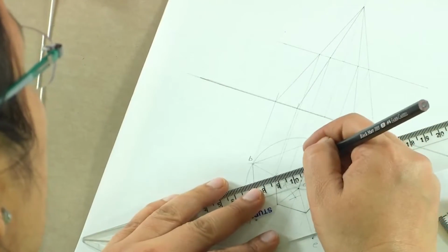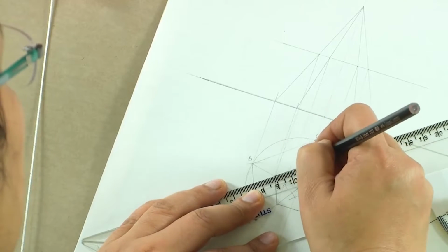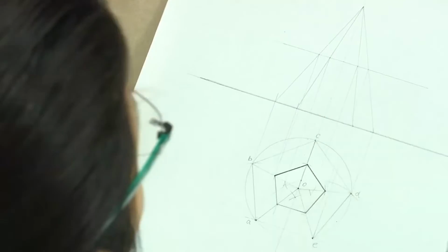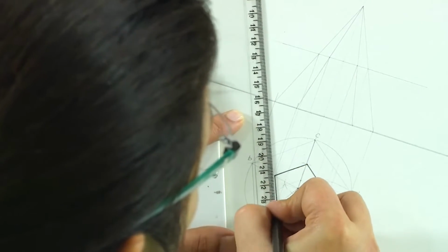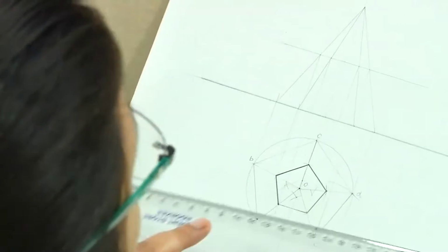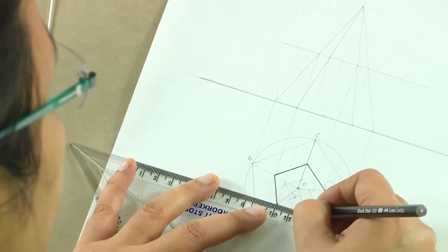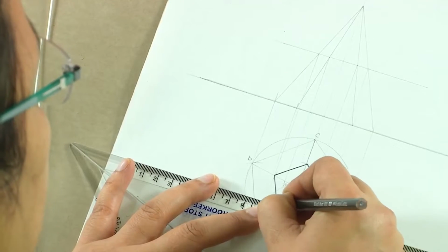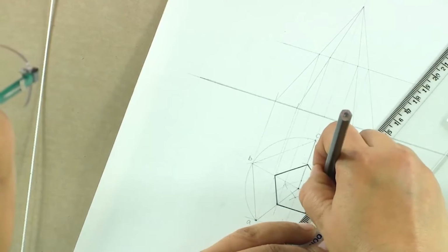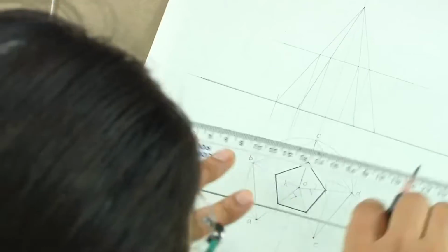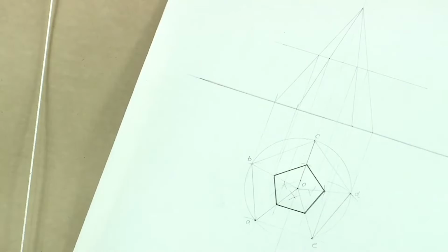we arrive at this point like this, and this is the final shape of the cut solid, a solid which has been sectioned. So, if you look at this, if I darken it, this is also the true shape of the section, which will be seen in its top view, because the plane here is parallel to HP, and that is why you see the true shape of the section in plan.